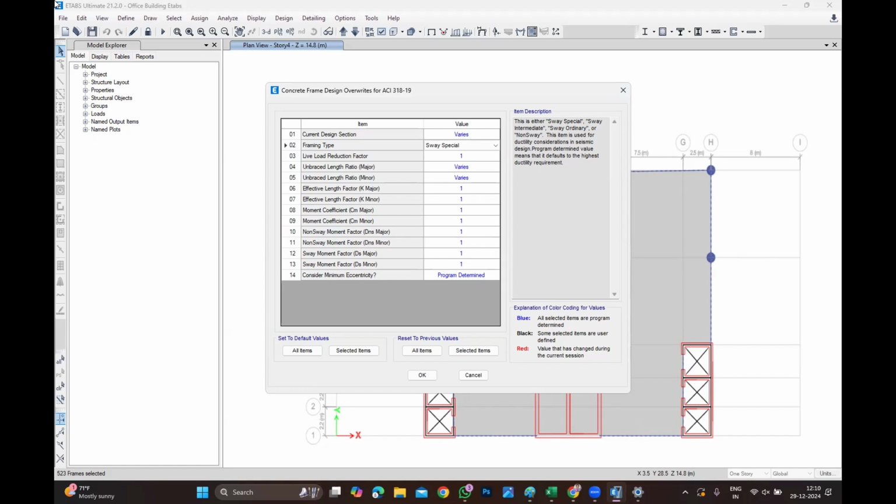Once the bottom bar is placed, the chair bar is placed, and the top bar is going to be laid, if someone comes and says I need to put extra rebar at the bottom, it's not that easy. It's not magic. You need to remove the top bar, remove the chair bar, and then add the bottom bar. Unless it is a massive raft with massive thickness, where people can walk and add it. If it is less thickness, 1 meter or 1.1, it's very difficult for people to approach. And nowadays you will say it's a more conservative design. You're getting 3 layers, 4 layers, 5, 6, 7 layers. You're getting the point.